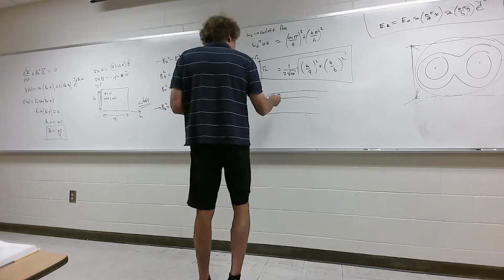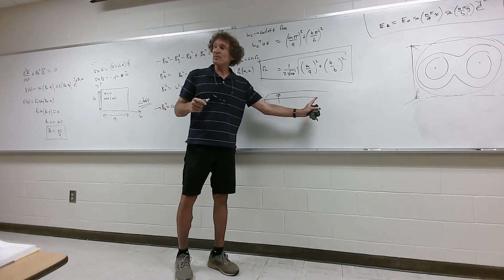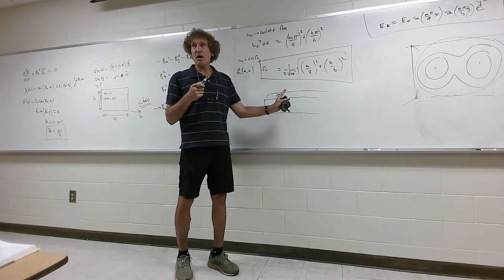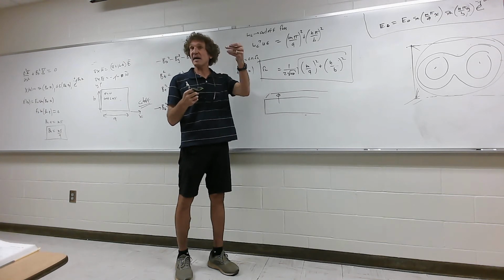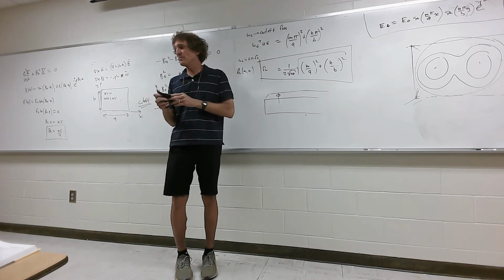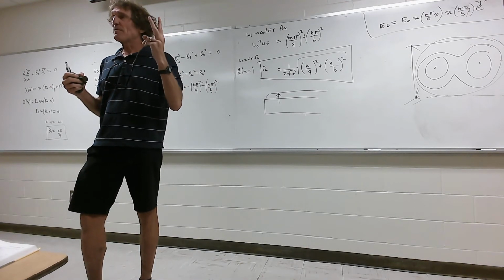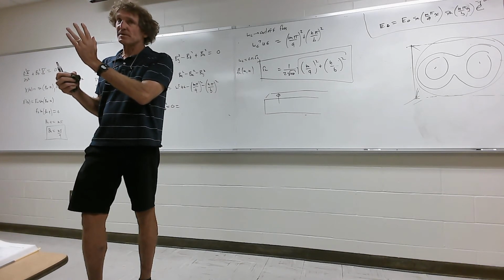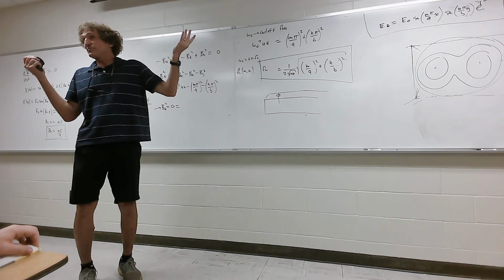Well, with a waveguide, when you hit it, if you're below the cutoff frequency, it rings, but it dies out real quick. There's no propagation. When you're above the cutoff frequency, that mode will propagate. And until you get this thing driving at a frequency beyond the second mode that it can propagate, only the first mode will propagate. That's important. Now, the reason that's so very important is you only want to drive one mode. If you have two modes propagating, the energy or the velocity will be different for each mode. And some of the energy will be at one mode, some at the other, and you'll get garbage coming out. You'll get a garbled signal.